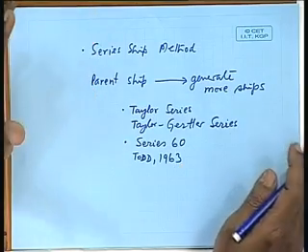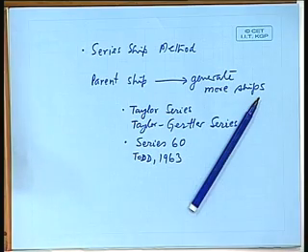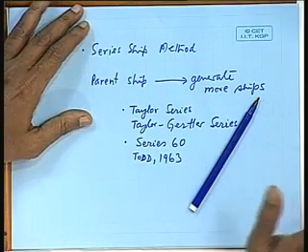Now, series 60's basic feature is that the forward sections are U-shaped sections. So, they have reasonably good resistance characteristics, and they are good to start a hull form at the initial stages of designing a vessel.